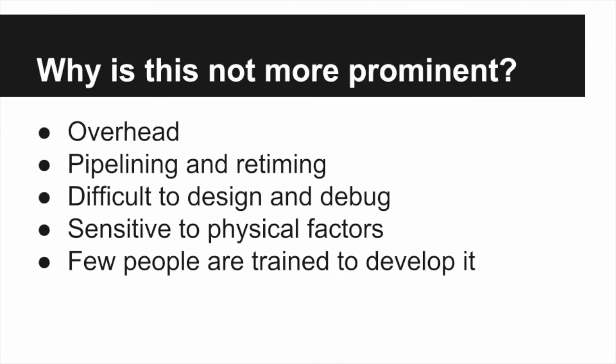The overhead may be up to double the number of circuit elements due to completion detection and design for test circuits. Essentially, the design for test circuits are required for debugging, and the completion detection, so in essence the handshake, requires additional circuit elements. So when combined with the fact that synchronous circuits have been getting improved performance over the last couple of years due to pipelining and retiming of their clocks, the actual improved performance over synchronous design is not as large as originally thought.